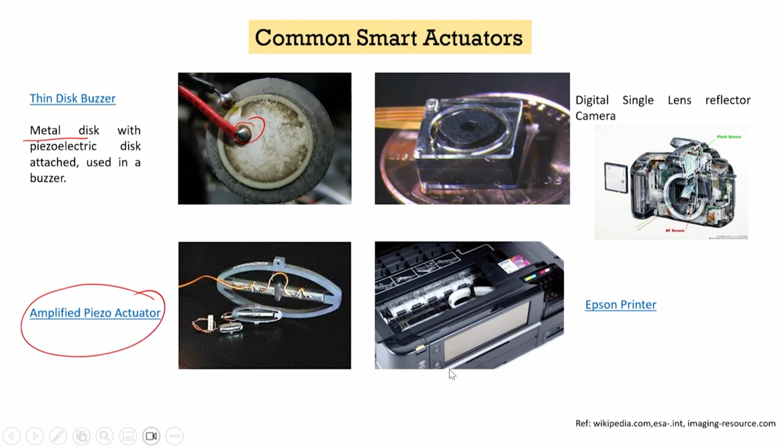Now, another application is for an amplified piezoactuator system. So, in the amplified piezoactuator system, the stack is here inside, and because the force is high, but the deflection is low, it takes into account this kind of a mechanism. Okay. So, what happens is, a large force here, because the stiffness is very high, will create a large change in the deflection in these directions. Okay. So, that is how the deflection or the stroke is taken from a 90-degree kind of an angle, so that you get maximum displacement out of the system.